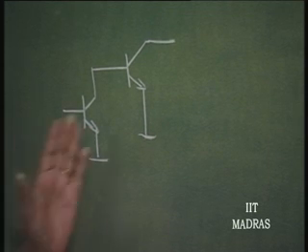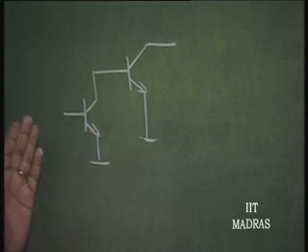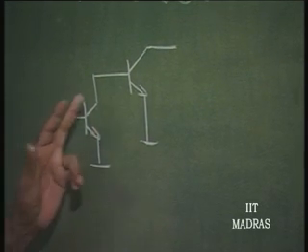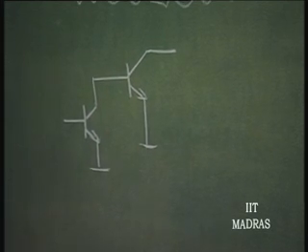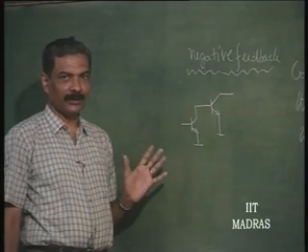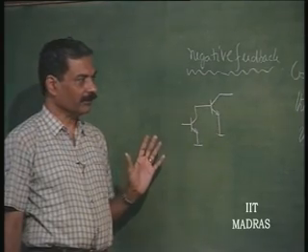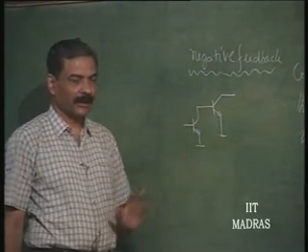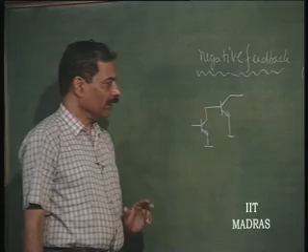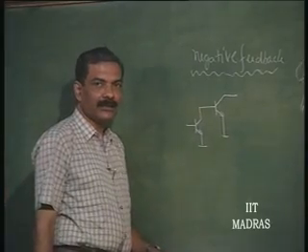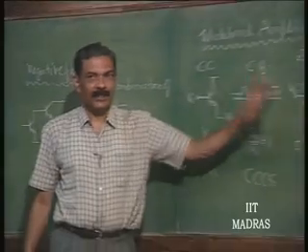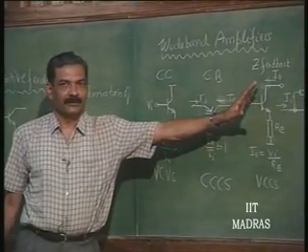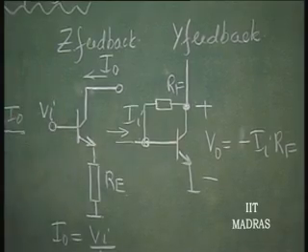Now, the moment you have two transistors, you have three time constants like input, intermediate, output, and therefore, it is likely to go into oscillations because of the three time constants, and therefore, it will need compensation. Whereas, these do not need any compensation, and they retain their wideband structure even while cascading.